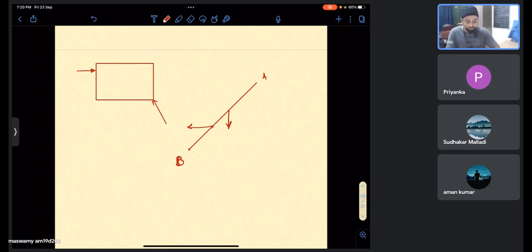Okay. So now, let us assume that there is loss of contact there. So the entire weight has to be borne by this point for it to be in static equilibrium. So what is the maximum frictional force that can mobilize here? It is mu N, and N is W, so mu W. So by equilibrium, this is also mu W. So this is so far so good.